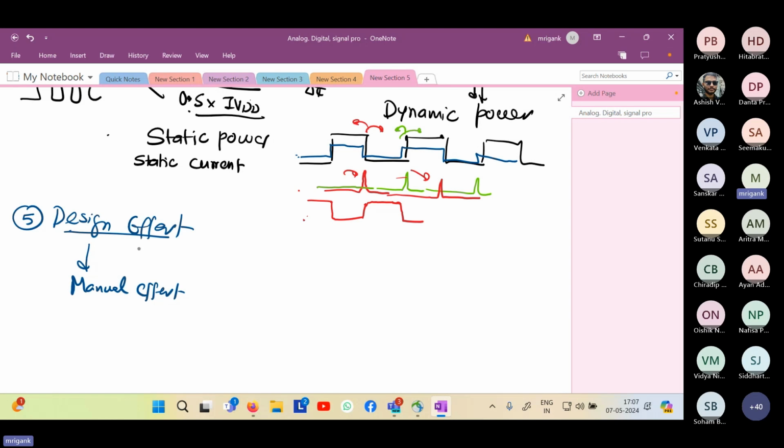Whereas in digital design, to a good extent, if you have code, there are tools which can convert that code into digital hardware, right? So it can be automated because it is algorithmic in nature. So we have an algorithm. Of course, if you are knowledgeable about digital hardware, you can optimize it much more. If you rely on automated synthesis, it may not be the most optimal one. You may still have manual intervention required, but digital design has been automated to a very large extent.